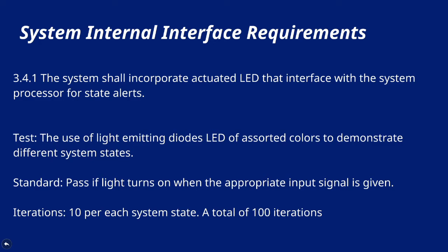The next requirement selected to be tested is the internal interface requirement. This test would implement the use of light-emitting diodes, LEDs, of assorted colors to demonstrate different system states. The pass or fail standard for this requirement would be based on the physical and visual verification of the LEDs turning on or off depending on the user input signal.